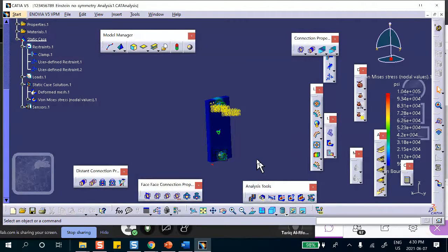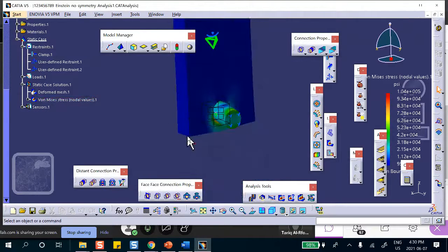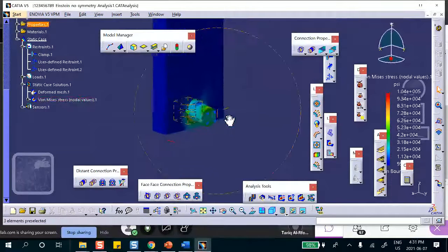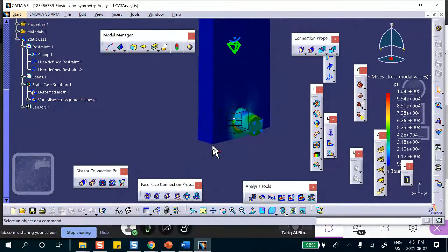Yes, for the block when you made a restraint on just one point. Is that an option? Can I just restrain a surface, a line, an edge? No, because notice what happens is this. By saying 1 point, do not move in the horizontal direction, it means that it can shrink this way. It should, right? But if you selected this edge and said, don't move, then this edge cannot shrink. It's going to stay the same size, same location.